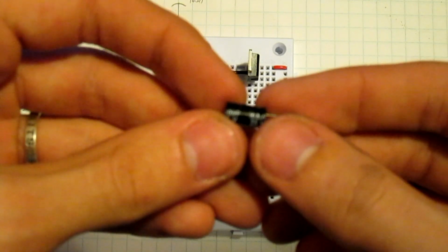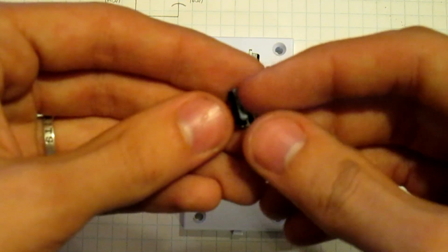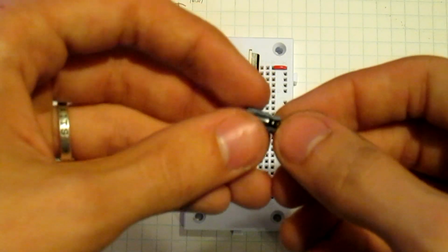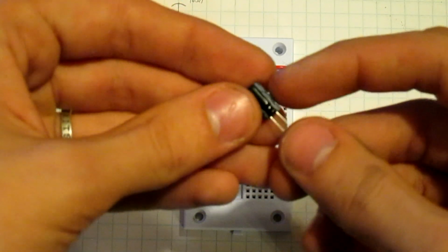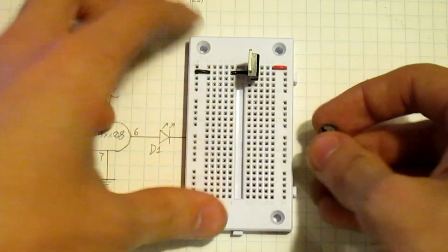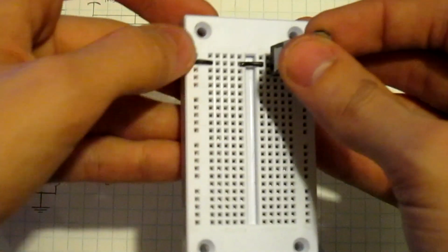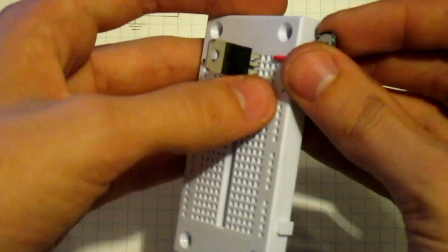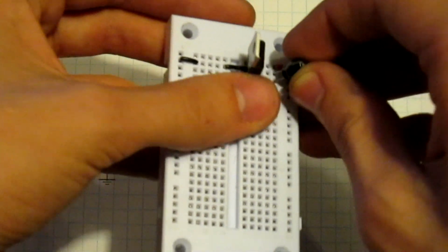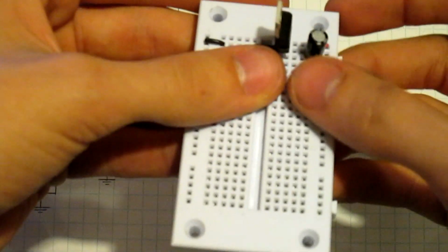You'll know it's 100 microfarad because it says 100, then it's got the Greek letter mu and a capital F. Capacitors like this Coke can have a stripe, and the stripe says hook that side up, hook the leg next to the stripe to ground. Ground is marked with the black strip that goes all the way over here, on the second row of holes, so we can hook the stripe leg right up there.